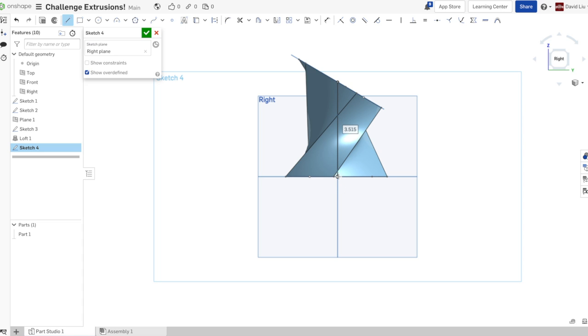But obviously, straight things are very uninteresting, so we're going to have to delete that and make some kind of arc. The reason we want this path to exist is we want it to be bent vertically also, and not just our horizontal bending by the match connection tool. So we want to use something called a 3-point arc. With a 3-point arc, you first select 2 points to indicate your start and ending point of the arc, and then you make the radius of the arc.